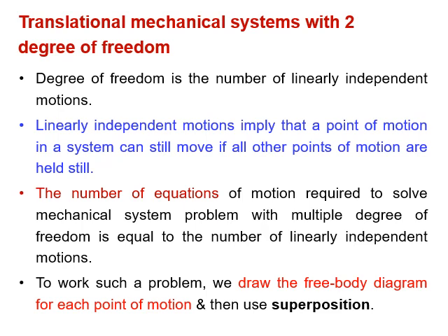For a system having more than 1 degree of freedom, the number of equations is equal to the degrees of freedom. That means if the system is 2 degrees of freedom, 2 equations are required to describe it. If the system has 3 degrees of freedom, 3 equations are required to describe it. To develop the transfer function, we apply what was discussed in the previous example, but we take each mass by itself, separately, and apply the superposition technique.